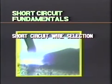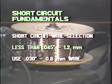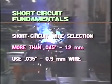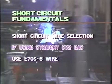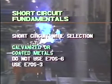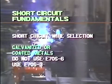Short circuit wire selection. When welding continuously on sheet metal less than .045, use .030 wire. When welding on sheet metals more than .045, use a .035 wire. If using straight CO2 gas, use a high silicon wire, such as an E70S-6. When welding coated or galvanized steels, avoid the E70S-6 wires. High silicon wires promote cracking. Use E70S-3.